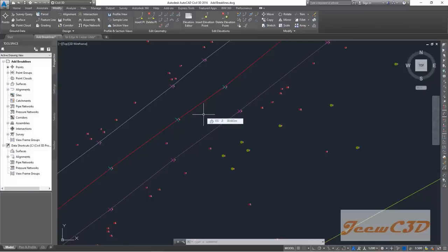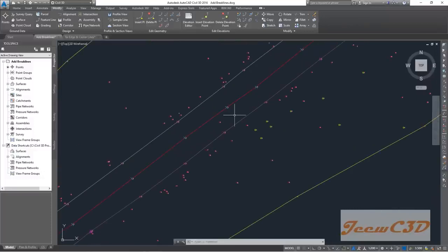Where the slope of an object can be identified without any problem, we call that line a break line. So you can identify the edge of the lane and center of the lane easily, and we call them break lines. In terms of a dam, the top of the dam will be a break line because you can see at the top the slopes are changing from that dam edge line. So that is how to identify break lines.